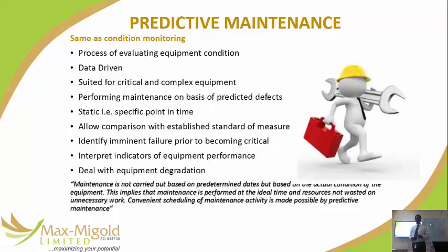Vibration tracking. Then for those who do oil testing as part of predictive, we'll look at some of the mechanisms for doing predictive. You can actually say this is what is going to happen with this equipment. And then even after you have taken those conditions together, you now decide on what to do. The condition may just be change oil, not change coolant. You understand? It could be wash radiator and change coolant. So you are taking specific action as a maintenance action, not servicing.